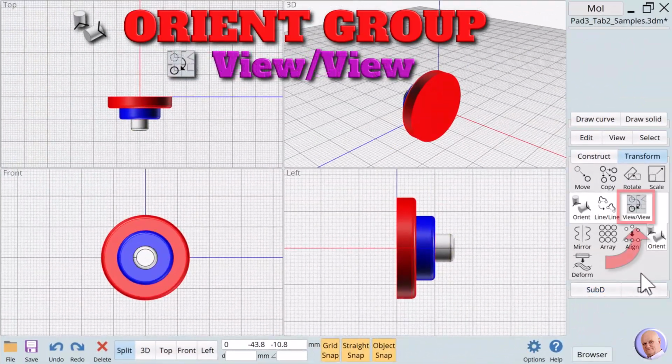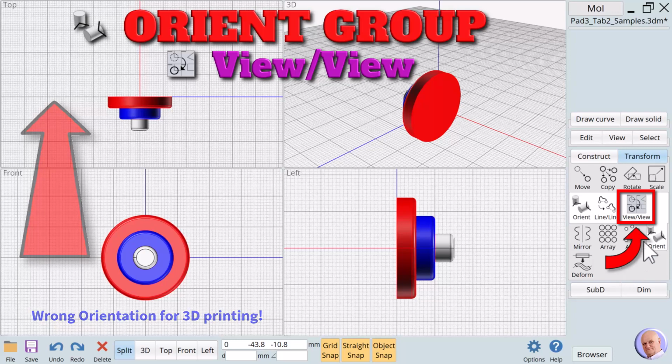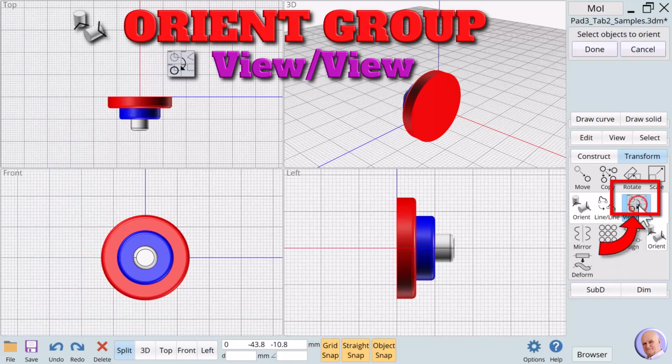The view-to-view method. Here is a split-screen view of a toy. For 3D printing, we need the object to be oriented in the top view, as it currently appears in the front view. It obviously was created in the wrong view for 3D printing. While this happens quite a bit, when students fail to pay attention to their starting view, it's not a huge problem. In fact, it's easily fixed using the view-to-view verb method.